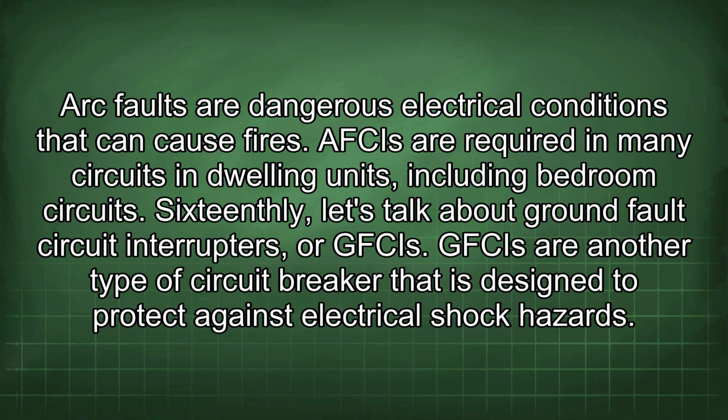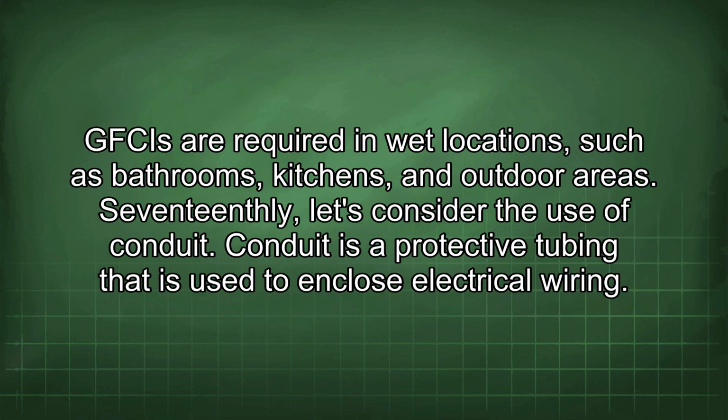16thly, let's talk about ground fault circuit interrupters, or GFCIs. GFCIs are another type of circuit breaker that is designed to protect against electrical shock hazards. GFCIs are required in wet locations such as bathrooms, kitchens, and outdoor areas.